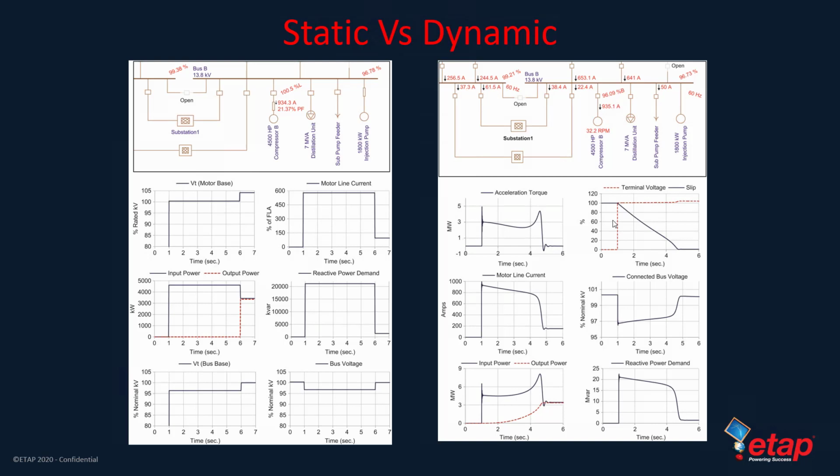But before, I'd like to go over the static versus dynamics in a more graphical form. And over on the left hand side, you could see how whenever we start a motor, doing a static or an impact motor starting, we see the graphs as piecewise function, which means that we get a worst case simulation on what's going on with the voltage and the current. However, it doesn't tell us the full picture. It doesn't tell us how long the motor will take to start, and most importantly, it doesn't tell us whether the motor starts or not.